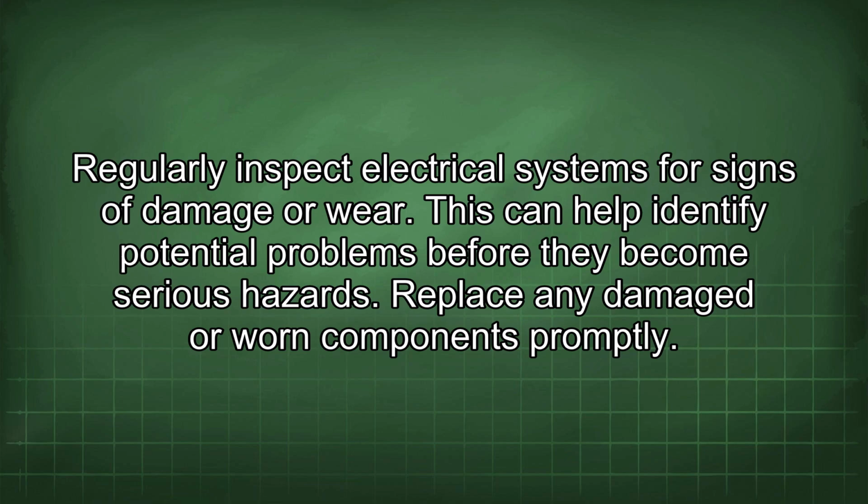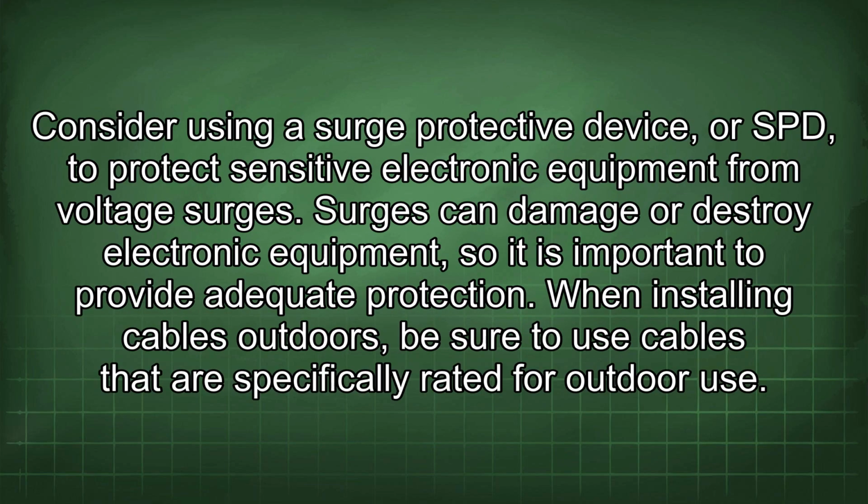Regularly inspect electrical systems for signs of damage or wear. This can help identify potential problems before they become serious hazards. Replace any damaged or worn components promptly. Consider using a surge protective device, or SPD, to protect sensitive electronic equipment from voltage surges. Surges can damage or destroy electronic equipment, so it is important to provide adequate protection.